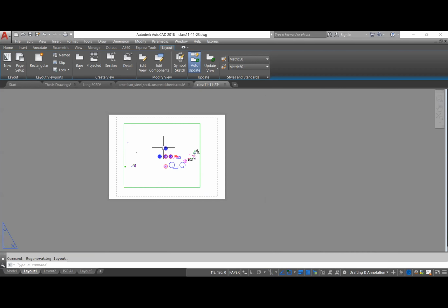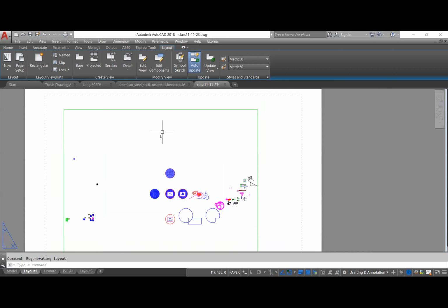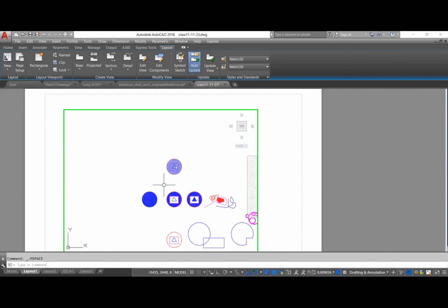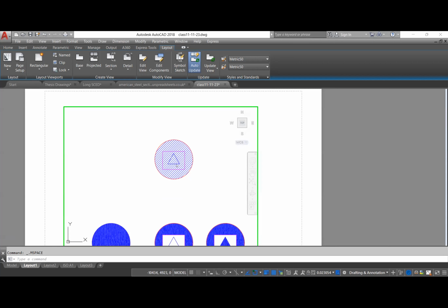What we need is to go into the drawing within the paper space. One way is to double click within that viewport. Once you double click in the viewport, see what happens. Your name has changed to model. That's like the model space. But because this is occurring within the paper space, we call it the floating model space. It's just terms. Now I can go in there, and you see the paper itself is not zooming in and out.